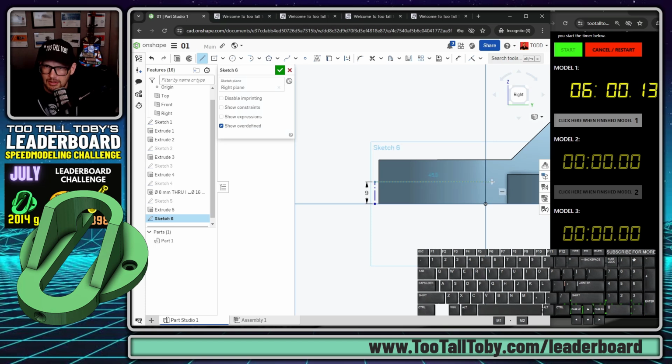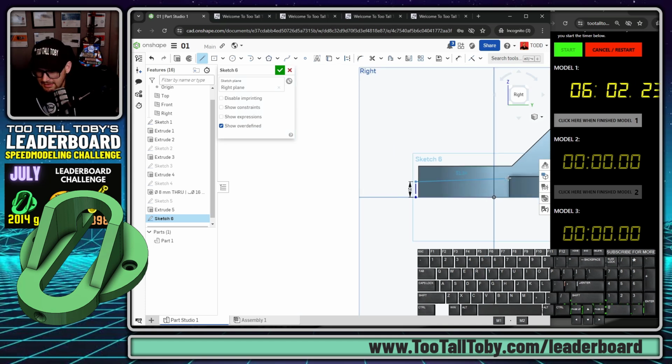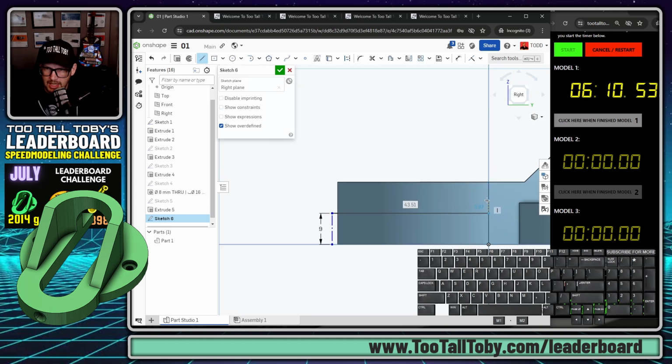And you really just need to go to beyond this inner wall here. So you could go up to this face here, and that should be sufficient to get you through that inner wall for this countersink. And then you're going to come up, and the distance you're going to come up here is going to be 1/2 of the hole, which the hole is 6, so that's going to be 3. You're going to come back to kind of this location, and then you're going to finish off with your countersink